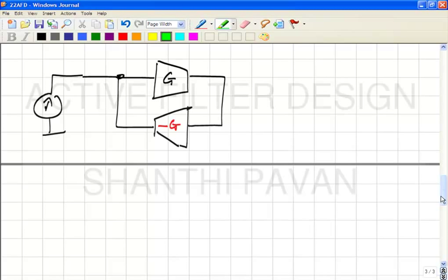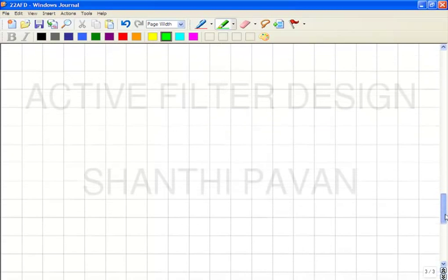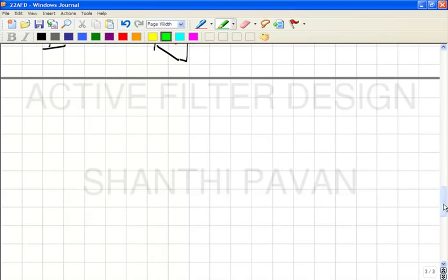For the Chebyshev, inverse Chebyshev, we had LC and parallel. We have not yet discussed filters with transmission zeros, right? These are all still all pole low pass filters. Now let's understand various non-idealities that a transconductor may have.